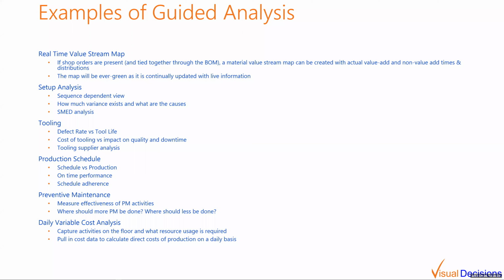Setup analysis: how do you do your single minute exchange of dies or your SMED analysis? How do you reduce that setup time? How do you commonize that across your different workers and so forth? How much variance exists? What are the causes for variance? Tooling information: I'll go through a specific example around tooling at the end of the presentation.